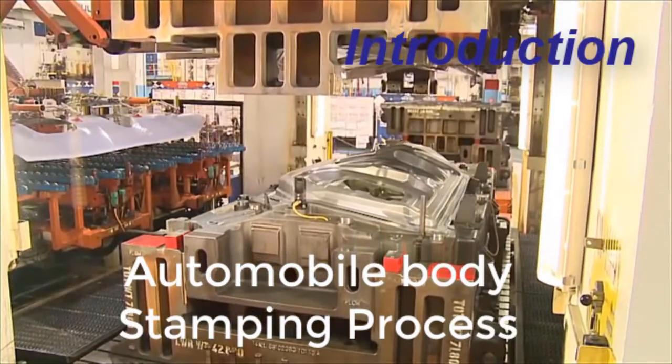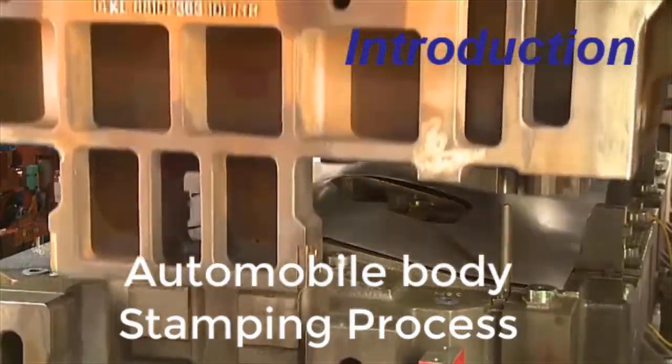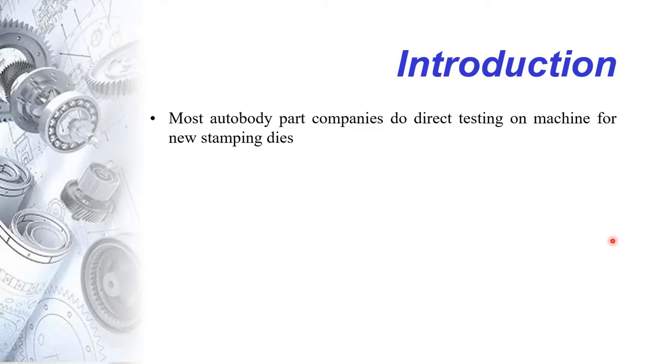The main equipment for this stamping part is stamping dies, and the stamping dies will be used in the stamping press machine. Most of these automotive part companies do direct testing on machine when they make new stamping dies. And of course, it needs about 7 to 10 trials and takes about 3 to 5 days.